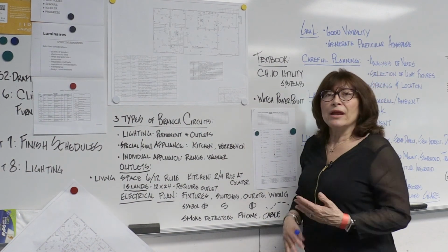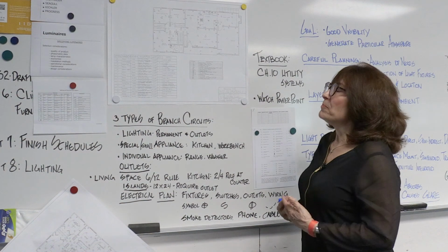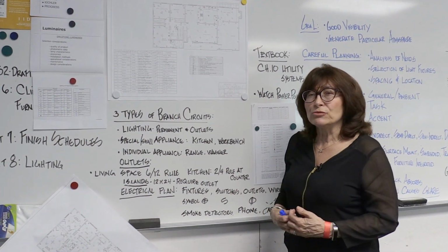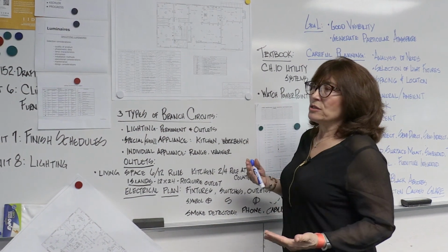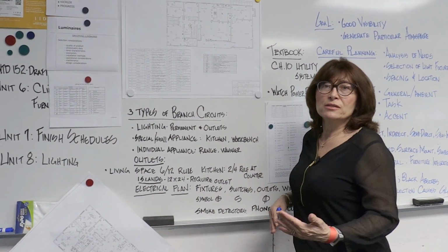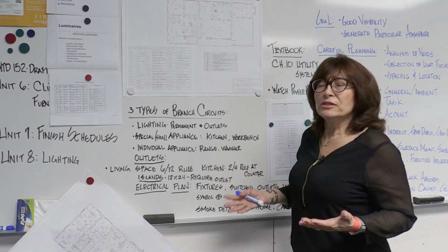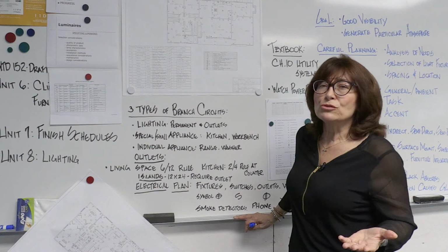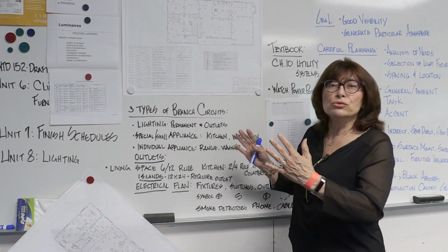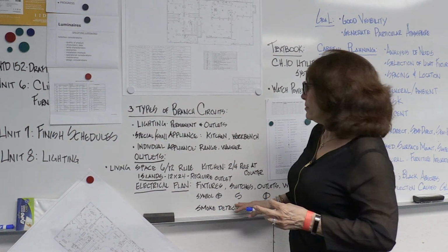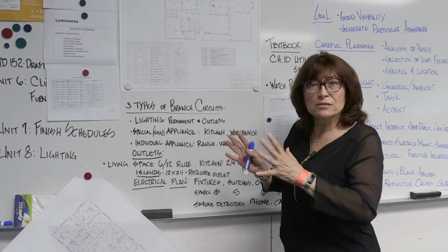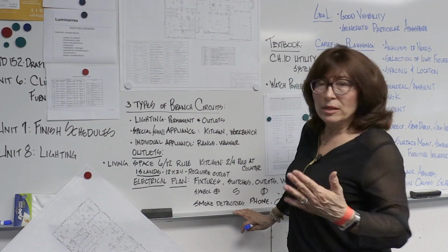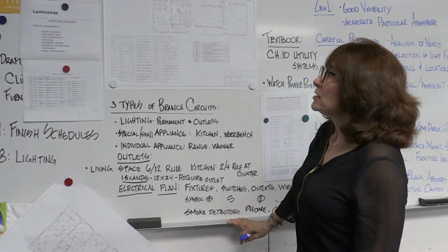You're thinking about how do you install it. An electrician installs these fixtures, but you want to think about the considerations of that. If you're installing a recessed versus something that is surface mount, there's a difference in installation method. When you cut a hole in the ceiling for a recess, there's a chance if someone cuts the hole too large, now you have to bring in a sheetrock person to fix something that may have overcut. So that may be more additional cost.